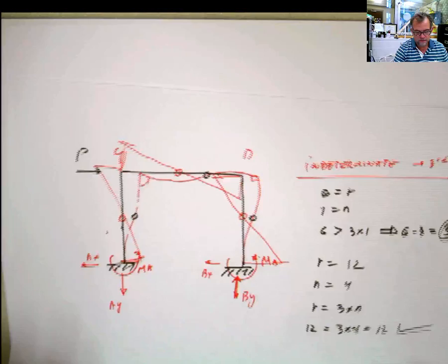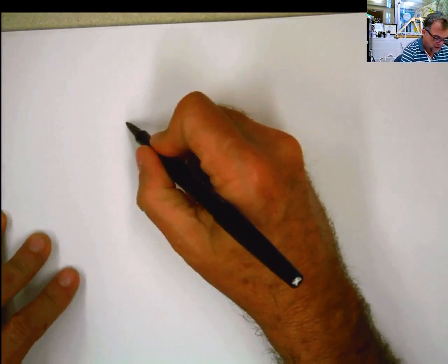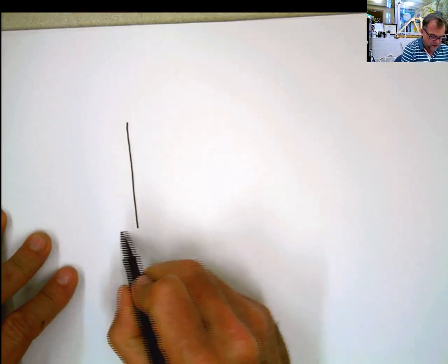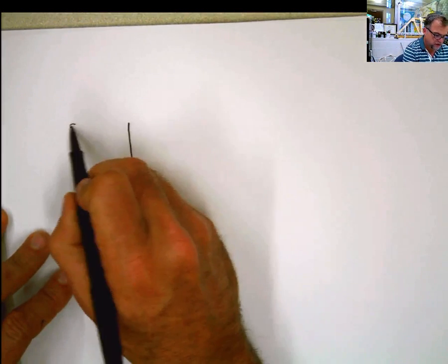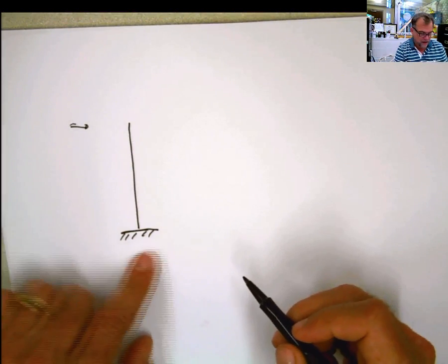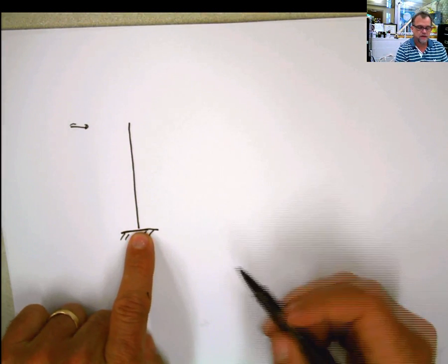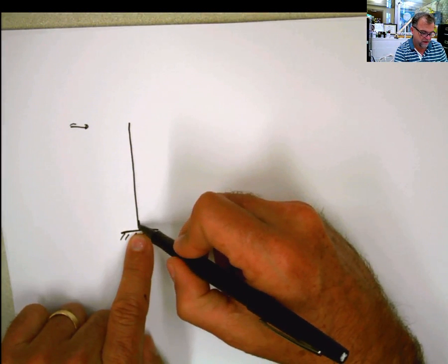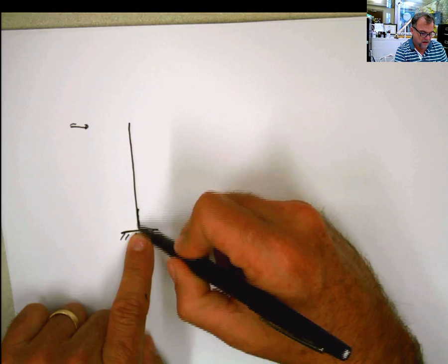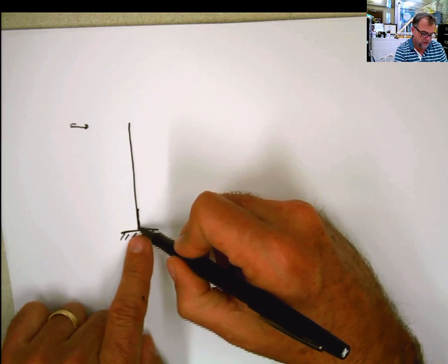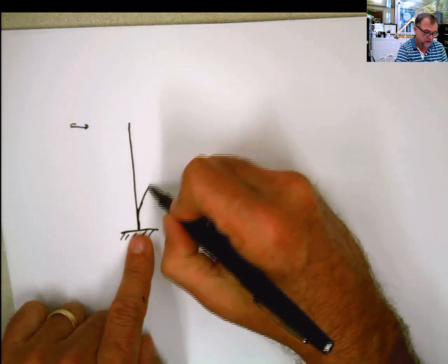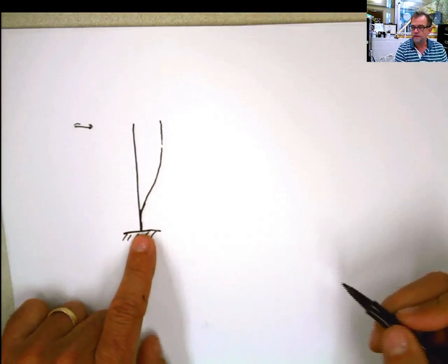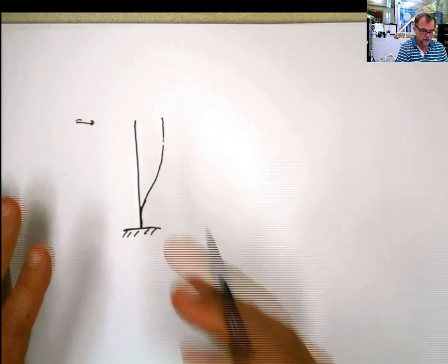There are, in every book, some conditions that you have, and you say, well, if this part here is a fixed support, for example, and this is subject to lateral loading that way, the rotation here is 0, the translation here is 0, so that means that my deflection has to start from this point at 0, rotation 0 here. Because this is going to produce a moment in this direction, this is going to deflect in the direction of the moment, something like that. But that's another topic, but you can see that.